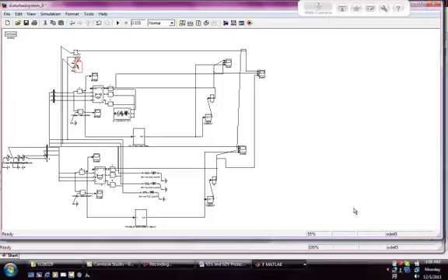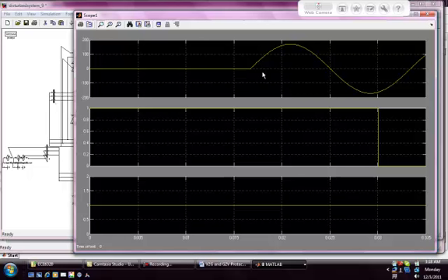Now the last scenario for the overcurrent relay is when the fault is on the house circuit while the electric vehicle is acting as a generation. This is a special condition because the electric vehicle breaker will trip before the house breaker, because the generator could be a source of fault, or it could feed more fault into the system. So we'll see that the EV generation will trip first before the house, and this is demonstrated in this